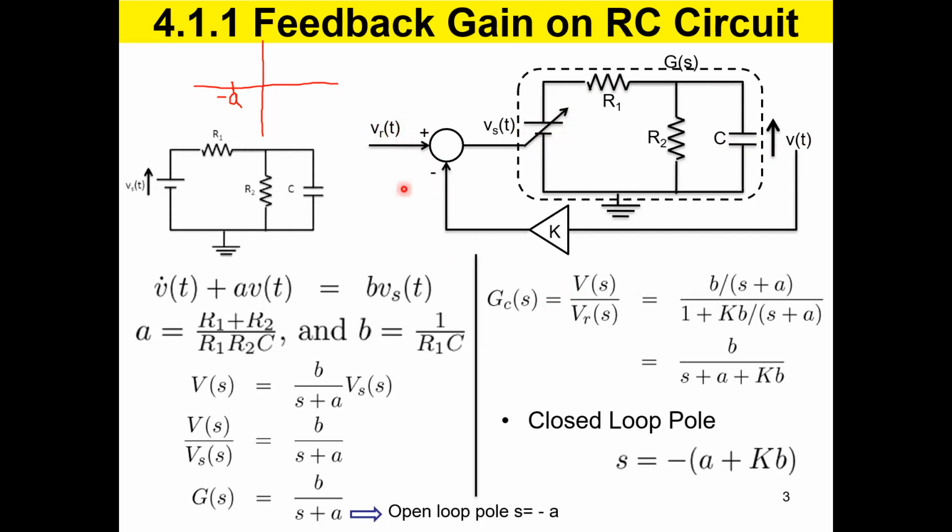So that is the new signal, the reference input. And if there's any difference between the reference input and the response, we know that we have to do something, and that signal we pass to the driving force. Therefore, the driving force is a variable driving force now, not a constant one. So it changes in a certain way so that the response becomes equal to the reference input. This is the basic concept of control systems, where you compare the response with what you really want it to be, right? The reference value. And then any difference between these two, you use it to drive the power source of the plant. Sometimes you increase power, sometimes you decrease power, until the reference and the response are equal to each other.